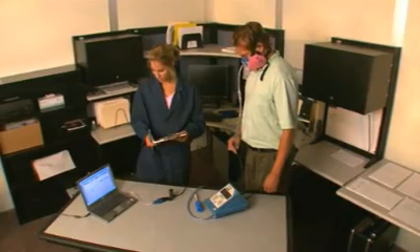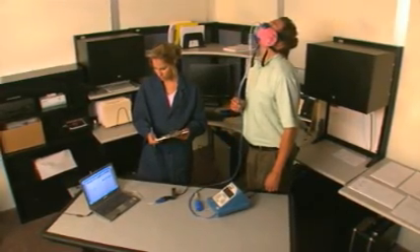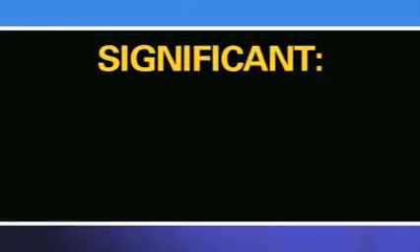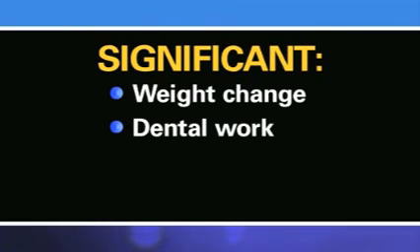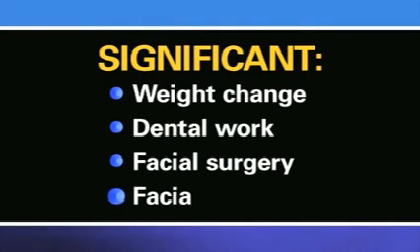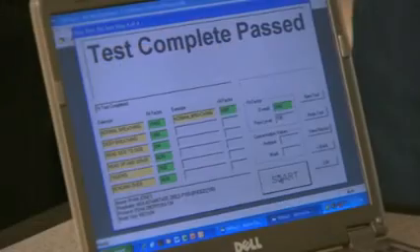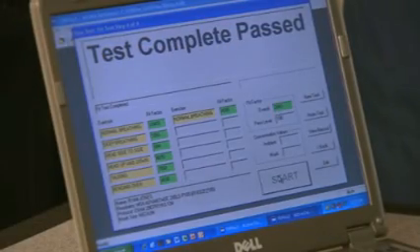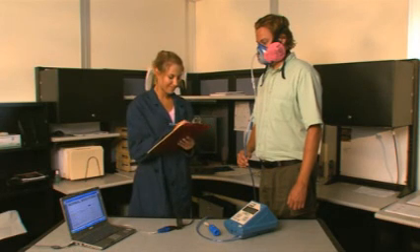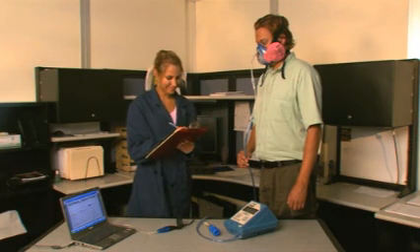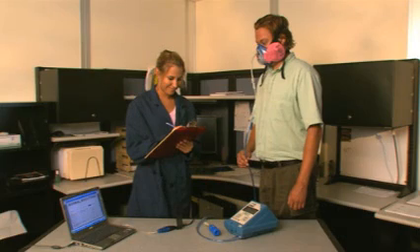The fit of your respirator must also be retested whenever you have a significant change in weight, significant dental work, such as new dentures, significant facial surgery, or significant scarring of the face in the area of the seal. When you've completed the fit testing process, it's very important that you know which make, model, and size respirator fits your face properly, and when and where you'll need to wear it for protection.